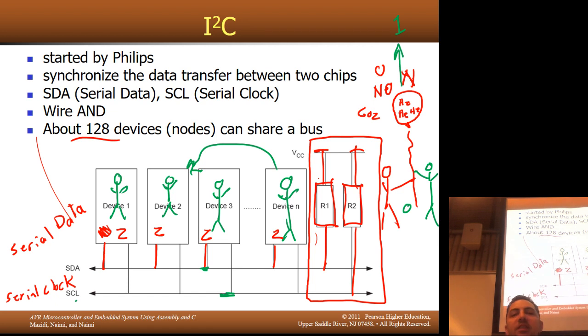Unfortunately, this is the easiest one to actually work through because there is a standard way. Unlike SPI, if we have multiple devices on SPI, you need clock, MISO, MOSI, plus however many select lines as you have devices. So it gets wire intensive after a while. I2C, up to 100 devices, all using the same 2 lines. So there's a higher level communication protocol, higher than the physical level. At the packet level or the frame level, we talk about how to talk to different devices.